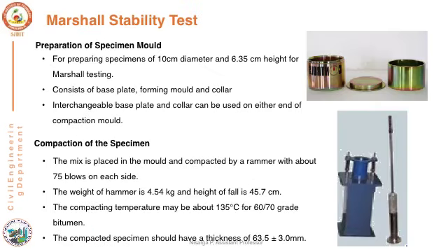We have already learned that the aim of any bituminous mix design is to determine the properties of aggregates and the proportion of the various materials used in the bituminous mix. The mix you get should have sufficient stability to satisfy the service requirement. It should have sufficient bitumen to ensure a durable pavement, and sufficient voids should be there in the compacted mix to provide a reservoir space for the additional compaction expected due to traffic.